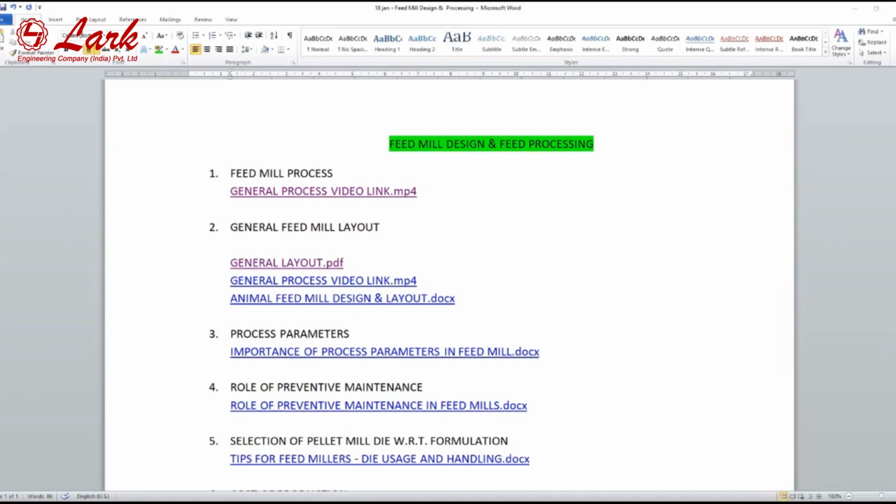So for 7,000 metric ton of grain, a 10 ton feed mill, and 500 to 700 metric ton of finished goods, we require 100 by 450: 100 in width and 450 in length. That is the warehouse we require to store that much material.